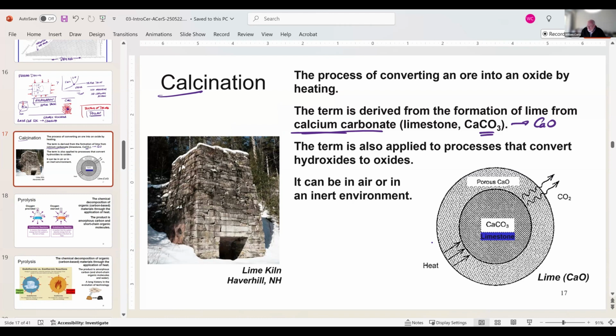General picture of that. Why is it porous? Because the density of CaO is greater than the density of CaCO3, limestone. So this means there's a decrease in volume associated with that reaction. It's a nice system because you put a calcium carbonate particle in there, it loses the CO2 from the surface somewhere around 900 degrees C. And then the calcium oxide layer that forms is a higher density, so it naturally cracks, and that facilitates the further elimination of CO2 from the center of that granule.